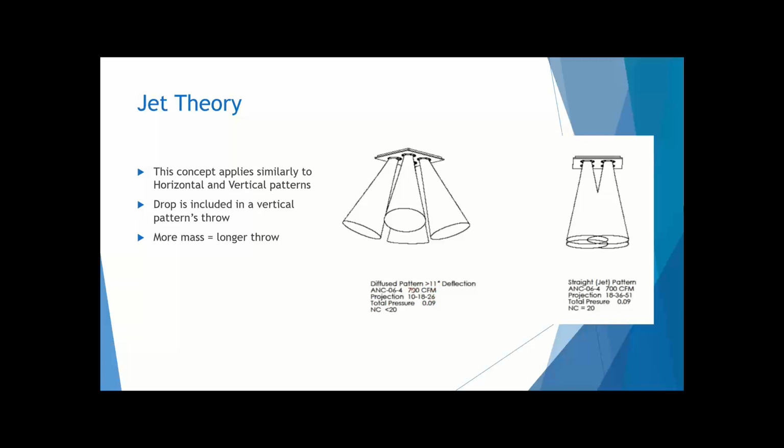So in this case, with these high bay jets, you're dealing with 400 feet per minute, 200 feet per minute, and 100 feet per minute. Note though, with typical smaller applications, let's call them low bay again, you're usually dealing with 100 feet per minute, 150 feet per minute, 100 feet per minute, and 50 feet per minute. But with these jet nozzles or other high bay systems, you're typically dealing with higher speeds. So that's why it ends with 100 feet per minute.